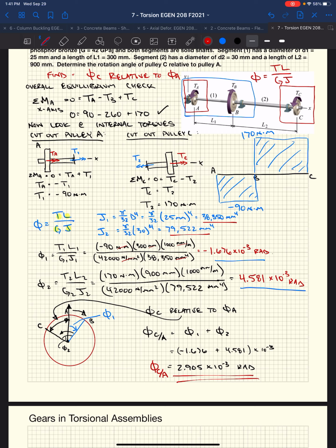And the shaft rotation and displacement is based on a torque over a given length. So at an instantaneous location here, that applied torque is really not doing anything to the deflection of the shaft. It's the fact that it's over a length that we accumulate this rotation. Like the green stripes here, as you twist that, it's got a linear rotation to it. And so here, it sees that there's no rotation.